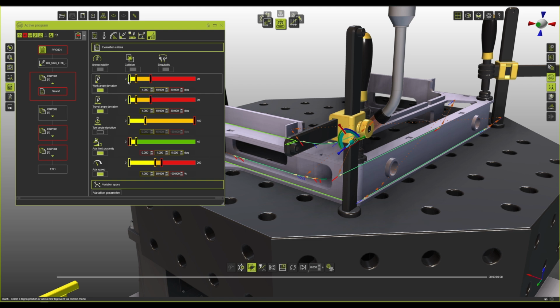In the arc welding process, we are putting this at 1 degree. And this is critical because anything above 1 degree starts to compromise the toolpath a little bit. The more it is modified, the more compromised the toolpath is. So in this case, we're establishing one range between 1 and 10 degrees, which is the yellow section, where we are saying you can modify the target between 1 and 10 degrees. And this is going to make it less optimal, but it is okay to optimize it within that range. We do the same for the other travel angle. So both for the work angle and the travel angle, we have these settings.